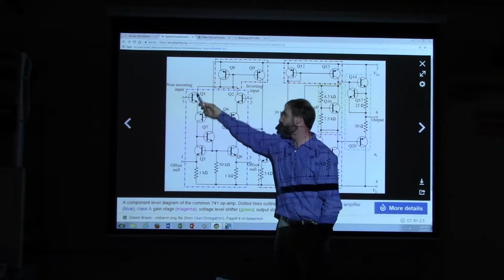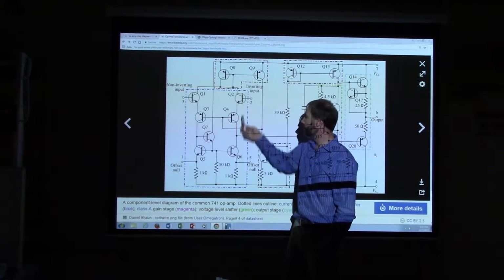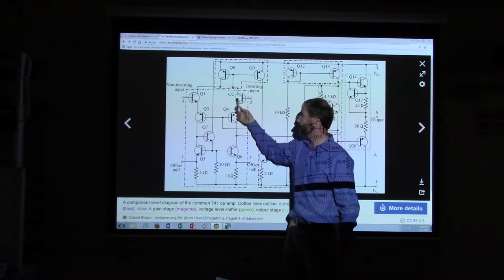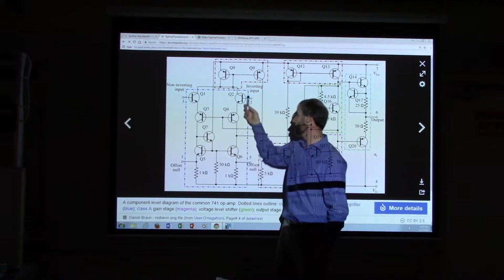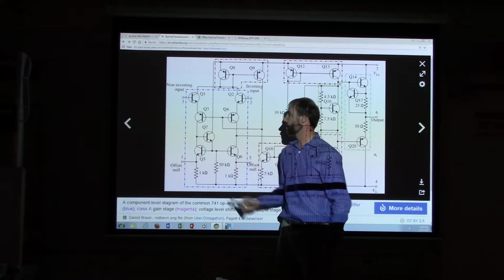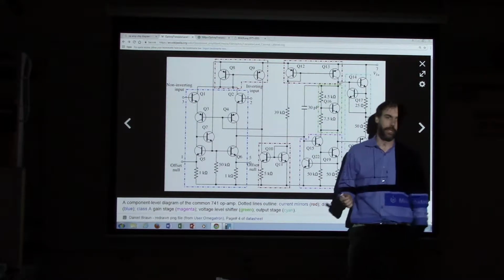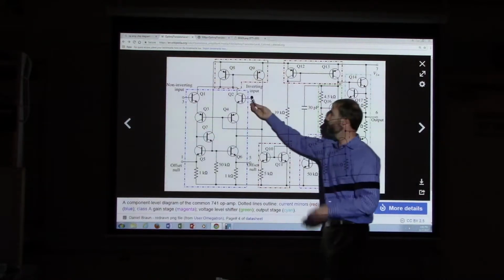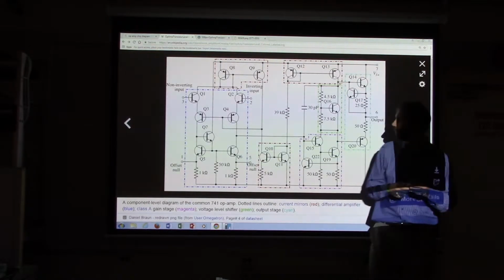And what happens is that you've got these two series of transistors that are vertical. They're sets of 3 transistors here and here. One input is connected over here, and the other input is connected over here. Together, these two sets of transistors create something called a differential amplifier. So it takes the difference between these two inputs, and it amplifies that difference.